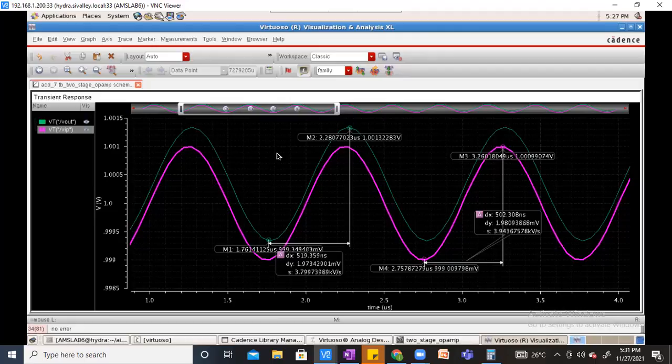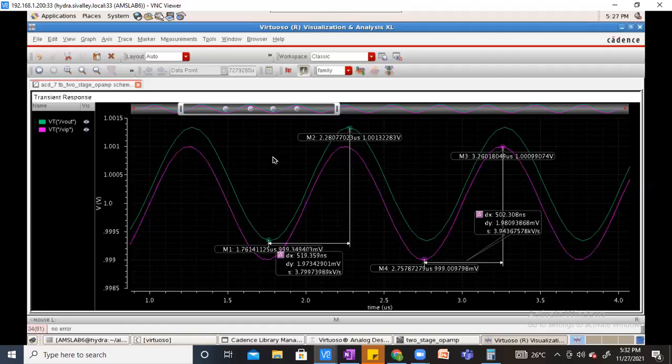You can see now we will do the slew rate simulation also, right? There you can see slew rate positive will not be exactly equal to negative because of your P and N mismatch. We have not matched the W by L of both N and P exactly, because we don't have fractional number matching here. It should be only a round figure. That is one thing causing that. The second thing is your mu n and mu p will not be exactly matched here because of that mobility factor. The third thing will be your mismatch, definitely, which is not there here, but definitely after layout you will get that mismatch.